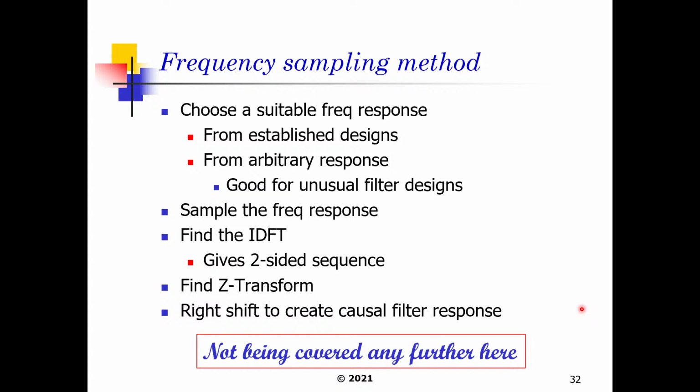We made sure to use the h of n equation with respect to sine. If you're using it with respect to sinc, please note that depending on whether you're using Octave or MATLAB, the sinc function is programmed kind of weird. So try your best to avoid using that sinc function. Use the sine function that we saw in the yellow shaded block, which will give you the correct results for the h of n values all the time.